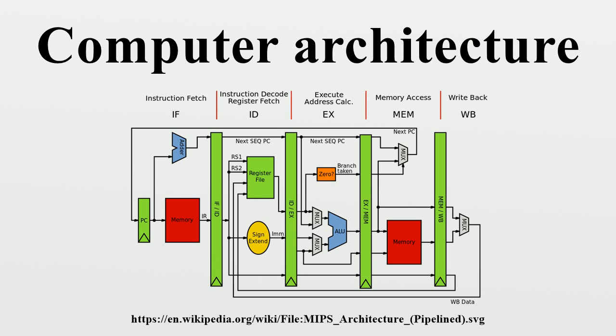Power consumption. Power consumption is another measurement that is important in modern computers. Power efficiency can often be traded for speed or lower cost. The typical measurement in this case is MIPS/W. Modern circuits have less power per transistor as the number of transistors per chip grows. Therefore, power efficiency has increased in importance. Recent processor designs such as Intel's have put more emphasis on increasing power efficiency. Also, in the world of embedded computing, power efficiency has long been and remains an important goal next to throughput and latency.